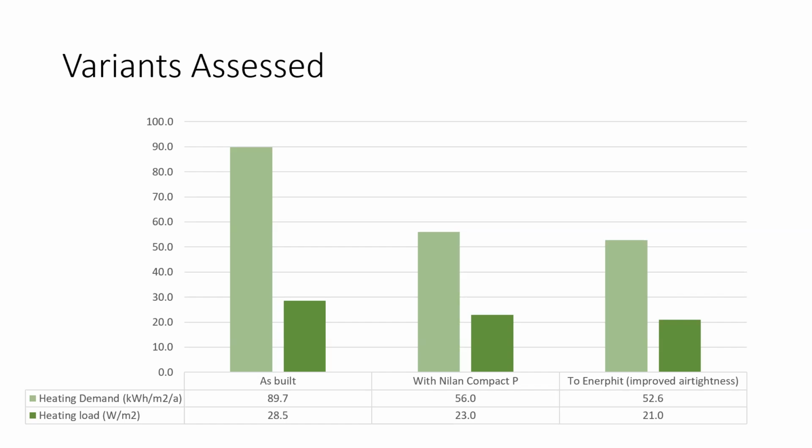Retrofit by the component method as it's built. And interestingly, the performance that you have here on the screen, the heating load and heating demand, if we had the building based on Dublin Airport data next to it, it would be 20% higher. So even between Dublin Airport and the actual location for this project, which isn't that far, I mean, they're both in the Dublin area, they're not that far away, it's a 20% performance gap, which is very significant.